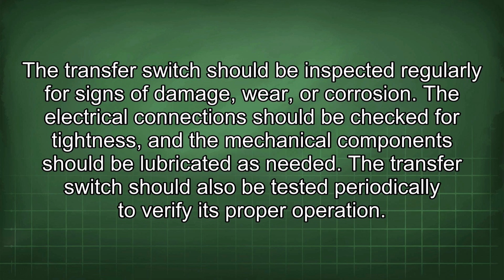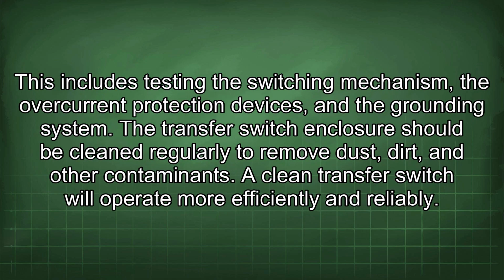The transfer switch should also be tested periodically to verify its proper operation. This includes testing the switching mechanism, the overcurrent protection devices, and the grounding system. The transfer switch enclosure should be cleaned regularly to remove dust, dirt, and other contaminants. A clean transfer switch will operate more efficiently and reliably.